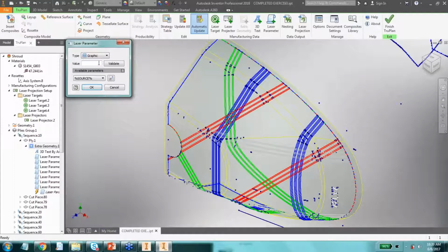What you would do is you would snap a digital picture of ply 1 in the real world after it's been laid down correctly, and then you would store that picture alongside your laser projection file. Maybe you want to call it ply1.jpg. Okay, so we're going to look for a file called ply1.jpg when we project ply 1, and it's actually going to show us a picture on the controller of that ply done correctly.